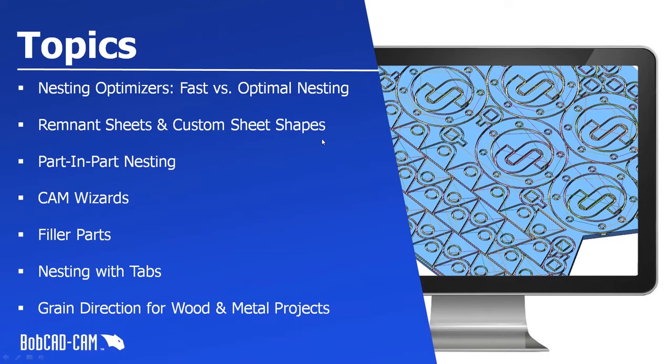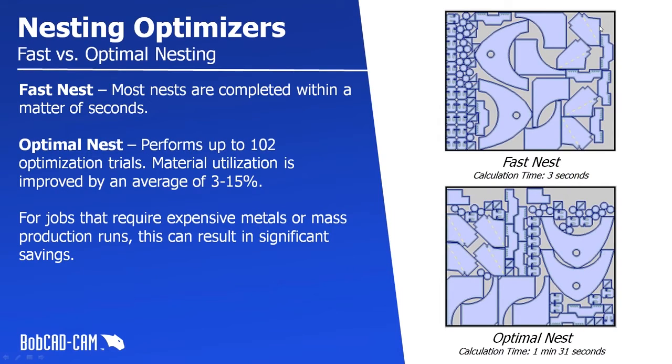Today, obviously, the thing I was talking about, we are going to go over the nesting optimizers, the remnant sheet options, the part-in-part nesting, the CAM wizard for nesting now, filler parts, nesting with the new tabs with lead-ins, and grain direction.